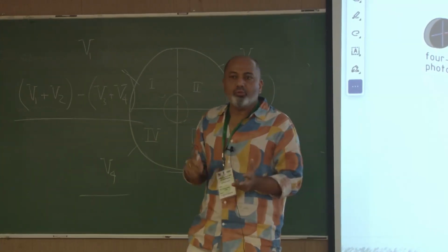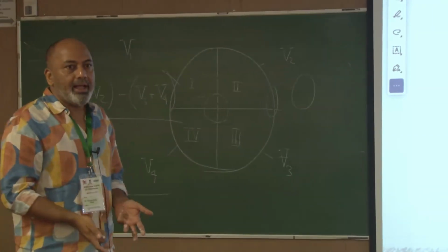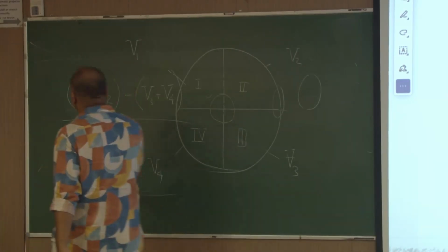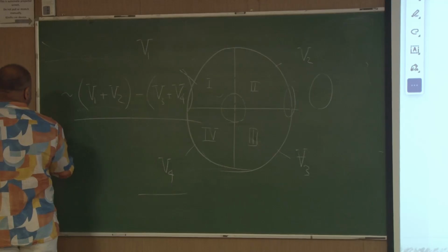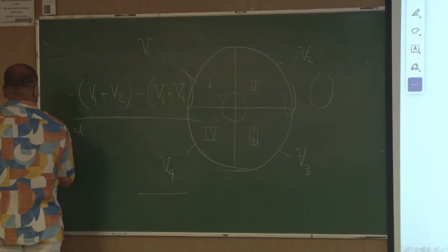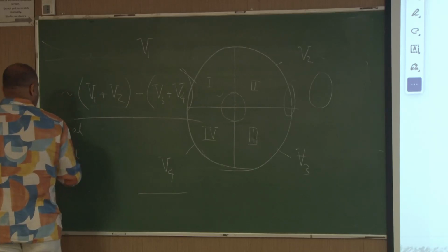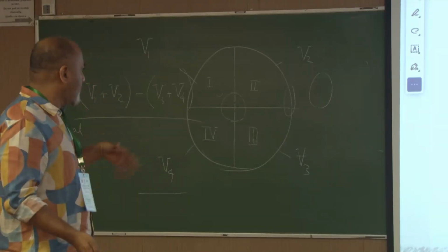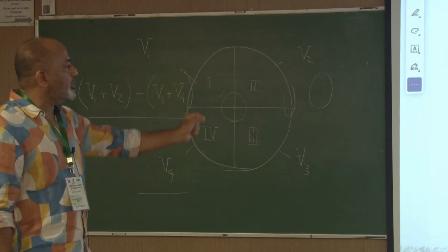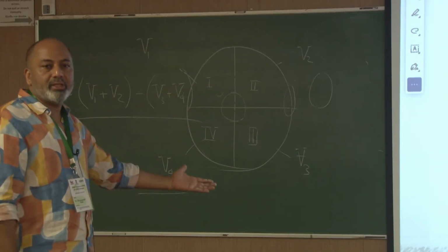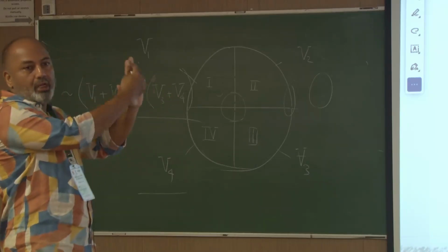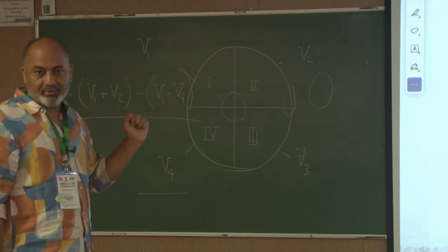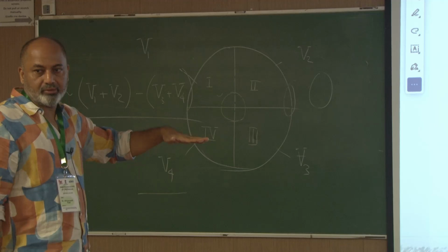So two things: one, you maximize the total signal, and make the vertical signal, as this is called, 0 with alignment, with maximum voltage of the total added together. And now if I bring the sample close and the cantilever is bent down, or you hit the sample and the cantilever is pushed down, then this will become positive, and you know that the cantilever is bent from its non-bent, or equilibrium, position.